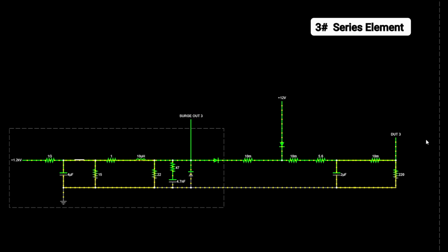So a series resistor needs to be sized with whatever the current on your board is, or you could change this to an inductor, which still will help more or less do the same thing, but for DC current, it lets it through, so you're not going to be dissipating that steady state power like you are with a resistor.